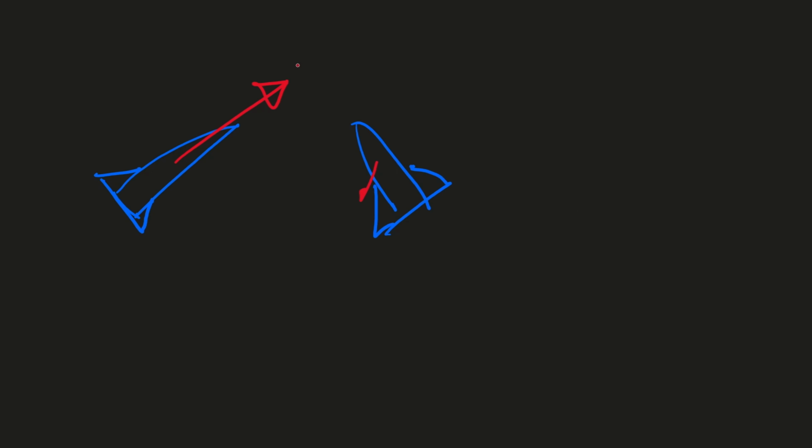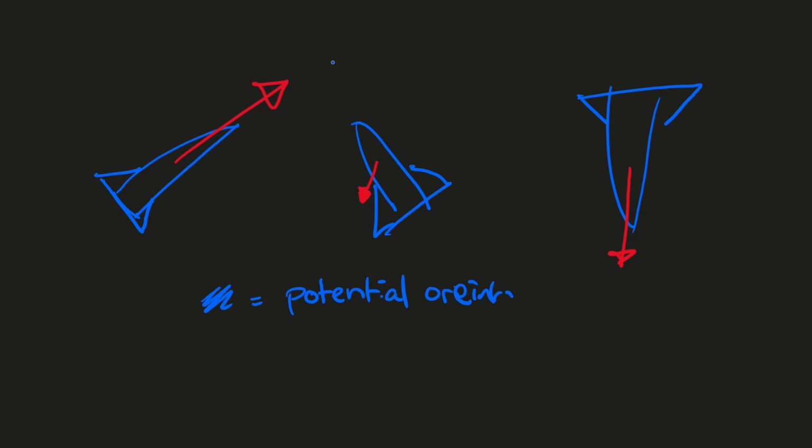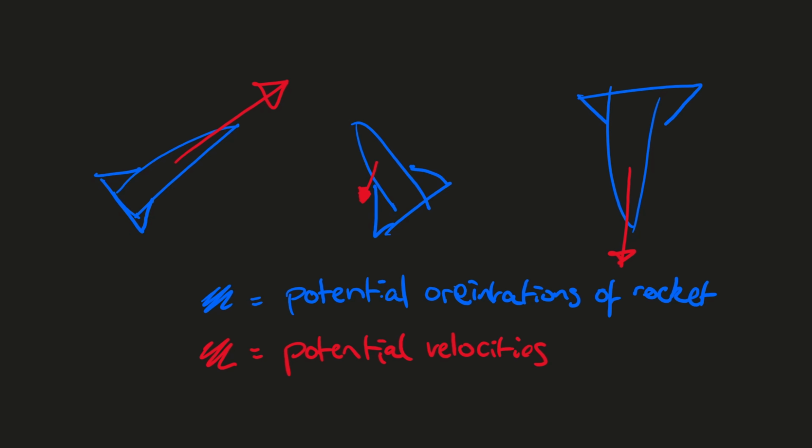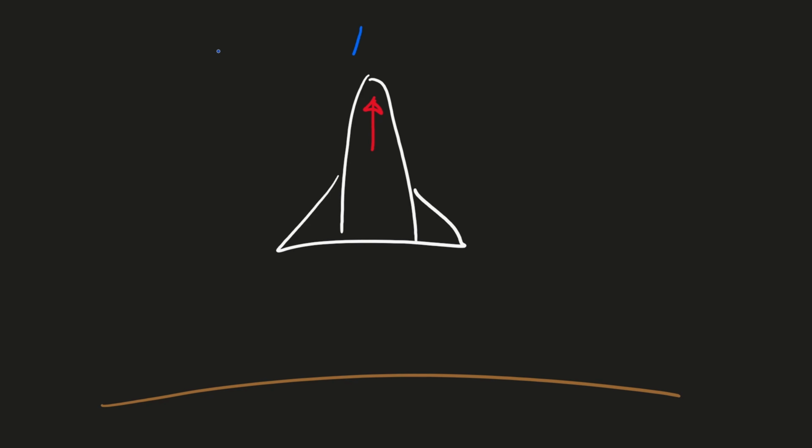To analyze these 2 axes, we're going to use a little magic called idealization. It's one of the important tools engineers use to actually be able to solve anything. There are millions of different states this rocket can be in, but what we're going to do is use assumptions, so we only have to analyze the exact case we want. First assumption we're going to make, the rocket is flying dead straight. And it's fair to assume this because we said we're using passive stability. On top of this, we're going to assume that the rocket's perfectly symmetric.